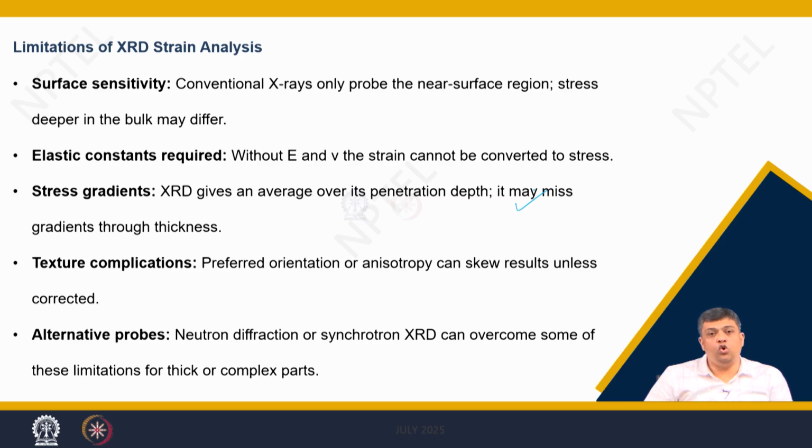If you have preferred growth, preferred orientation, or anisotropy in the structure, then it can complicate the overall analysis. Hence, there are techniques which are used to supplement the results obtained using X-ray diffraction studies at the laboratory level, and these techniques are like neutron diffraction or synchrotron high resolution X-ray diffraction studies.